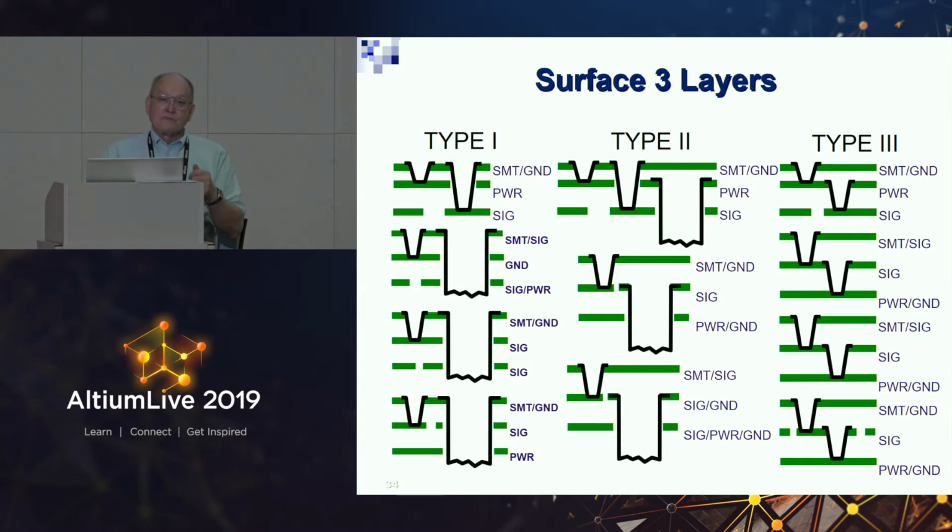But the other thing is that, and believe me when I tell you, if you move layer 2 to layer 1, you will gain 20 to 25% more return path. Now, the engineers violently disagree with me until I take their artwork and bring it up and say, all right, let's measure the amount of copper on layer 2. Okay, let's merge it into layer 1 and measure the amount of copper. The amount of copper increased by 25%. And they said, how is that possible?